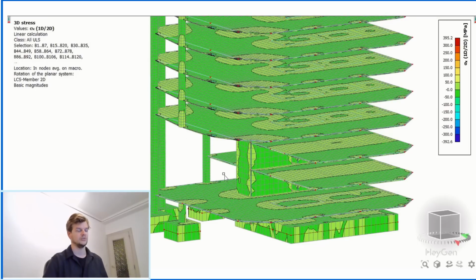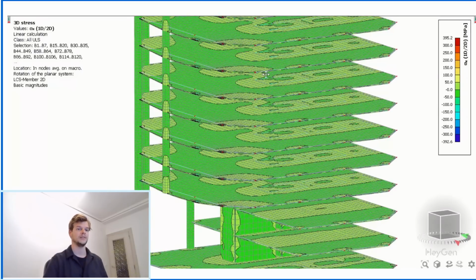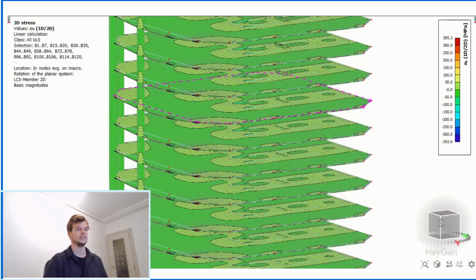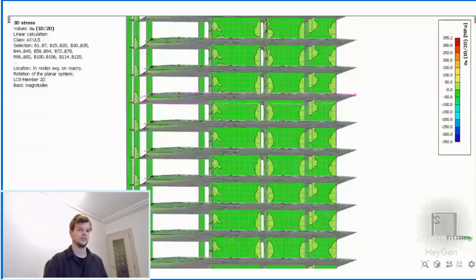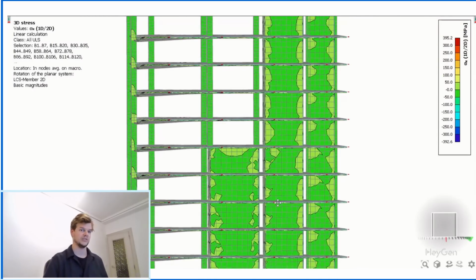That's dangerously close to, or beyond, the capacity of most concrete elements, knowing that the top part has a lower quality concrete. The building has no alternative load path, no redundancy, and just like in reality, the entire structure gives way. This collapse shows how one weak link, like a soft story, can bring down an entire structure.